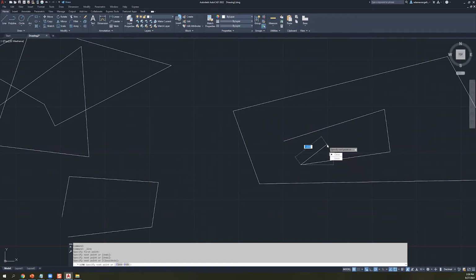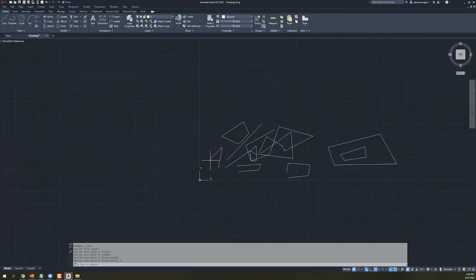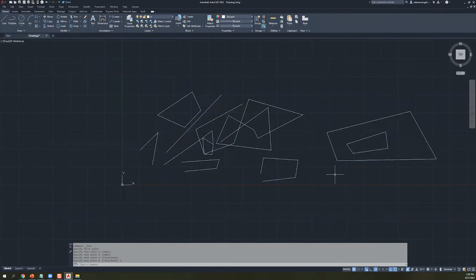And you'll notice that once I have 3 line segments down, if I press the arrow key down while my command is active, I'll actually get some extra options over here, including close, which we just saw on the right click, right? So that's actually 2 ways to get to this close command if you need it, right? And so I could hit close and hit enter, and those are both ways to close geometry. Do we need to do that? Kind of, sort of. Let me talk about that next, and I think we might talk about that after the break, in fact. But yeah, that's just the early intro to drawing and placing down geometry.